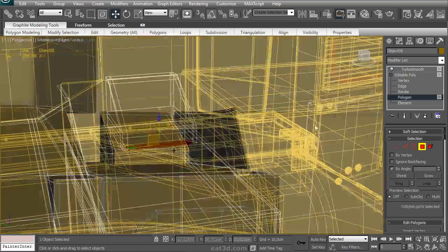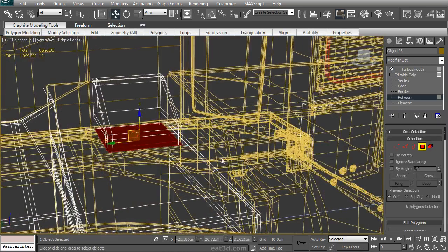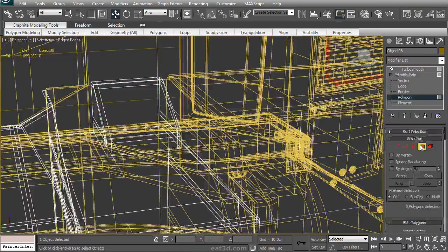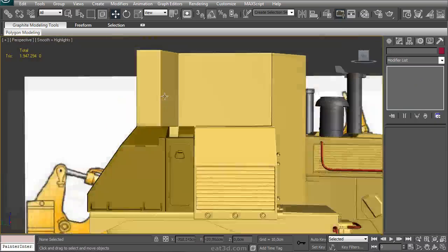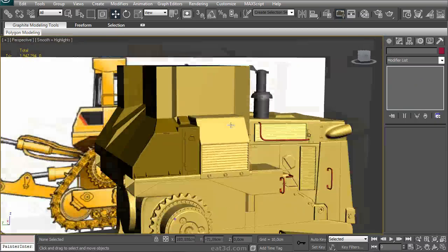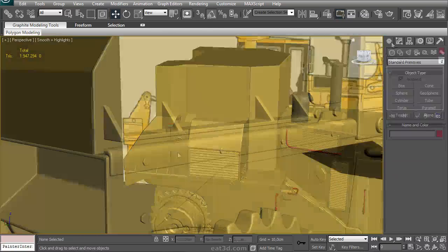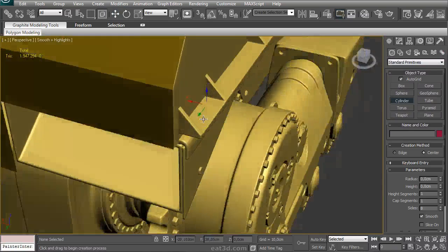And I forgot to delete the bottom, and that's messing things up, so select one, hit grow, hit grow again, and delete. Why am I using grow? Well, I would have to select the tiny edges around the edge that take care of the smoothing. I would have to select them manually. If you use grow, it's just a simple trick of doing things faster.